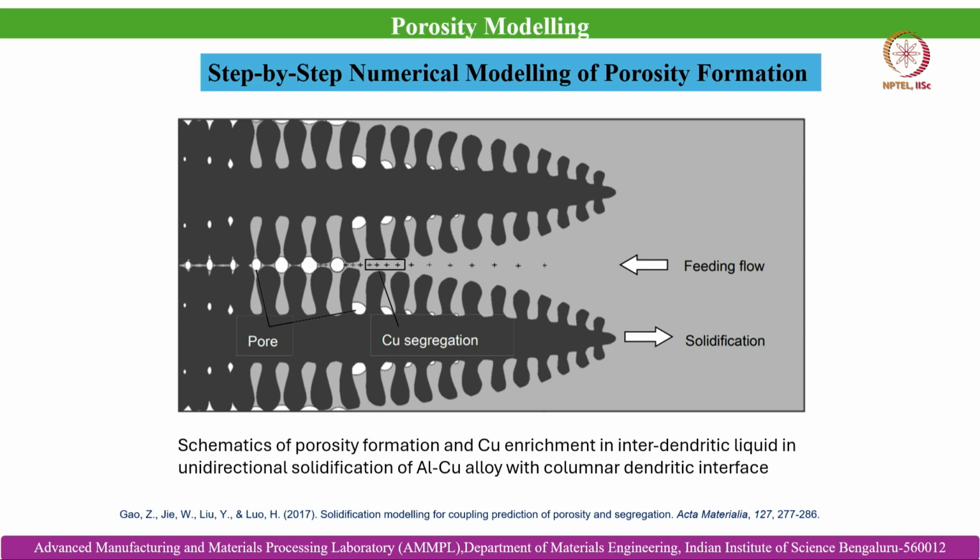So we will further discuss porosity modeling. Like I discussed in the previous slide, you can see these locations. These are the interdendritic locations where these porosities get trapped. These bubbles get trapped, and later, as solidification of the part evolves, they become microporosity. These bubbles' shape is totally dependent on the evolution of the microstructure. Their shape, their radius of curvature, changes with the secondary dendrite arms.